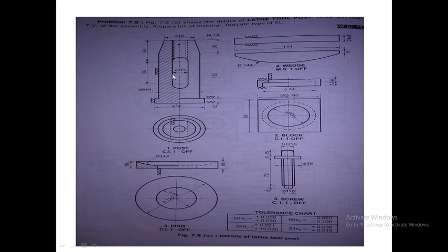So since here the dimension is given as 24 mm, the length, the wedge which is of width 24 will be inserted inside this slot, and over this wedge, that is over this rectangular surface, we will place the cutting tool. Now the top view, of course this part is cylindrical in shape, so the top view will be circles. So this outer circle will be of diameter 72 mm. This second circle which is visible will be of diameter 60 mm, whereas the third circle, this circle will also be visible, so it will be of diameter 48 mm.